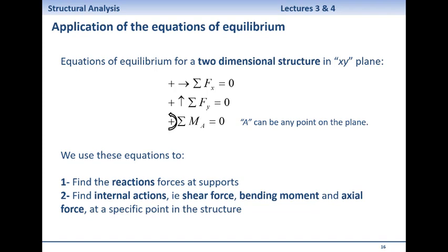In this particular case, the moment that I'm applying about this point is this force with full capacity, because it's perpendicular, times that distance. If I ask you what is the moment of this force about the handle, it is 0.